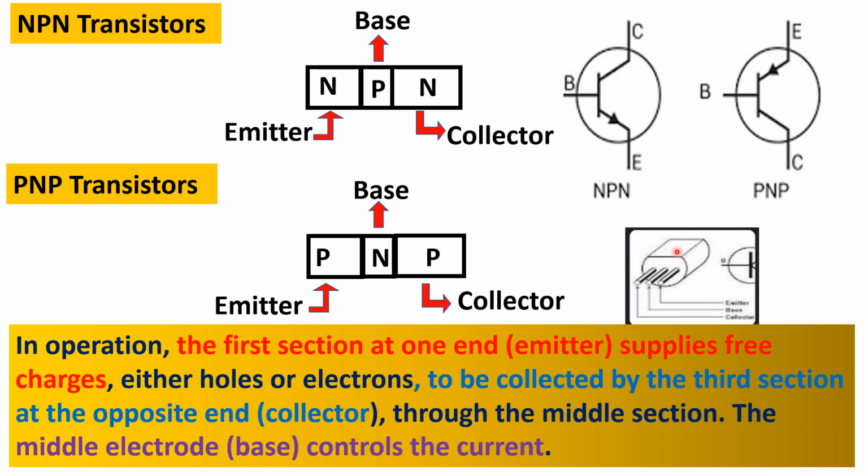It is the flat surface that is facing you, and the first electrode to your left is always the collector. Of course, the one in the middle is the base, and the one on the right is the emitter. So that's always the rule in determining which electrode represents those three layers, whether it is an NPN or a PNP transistor.